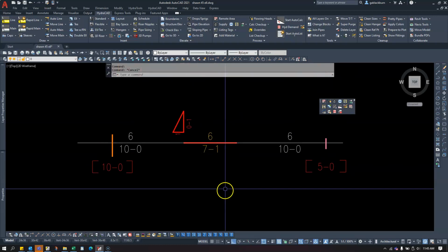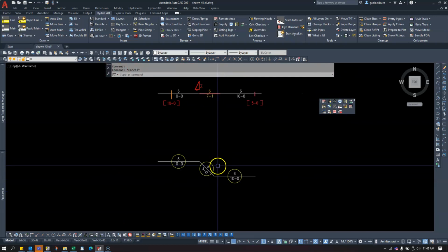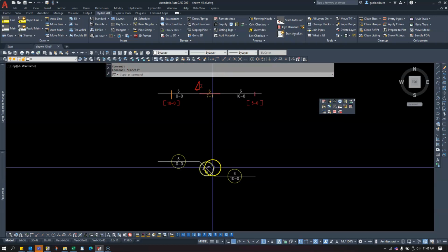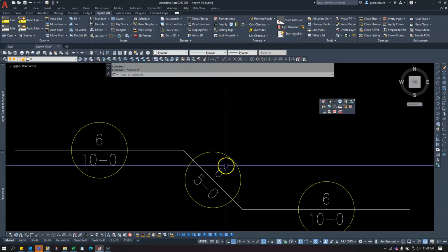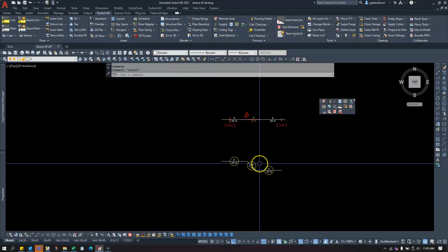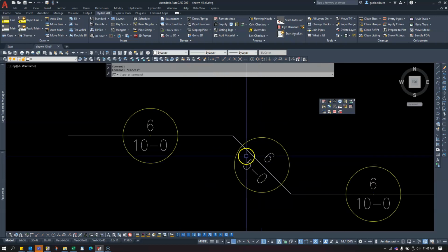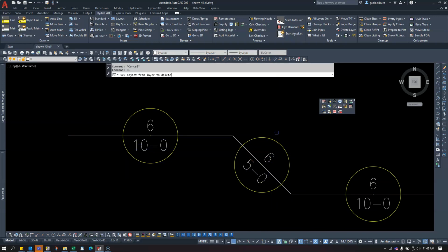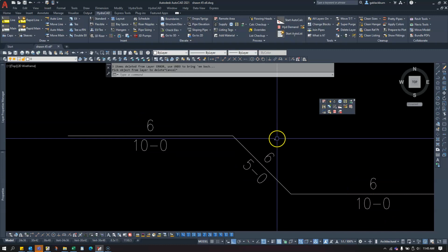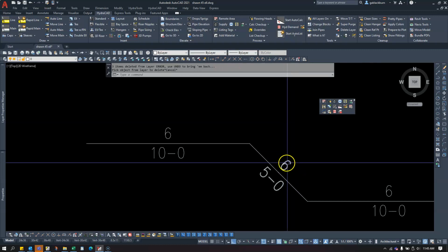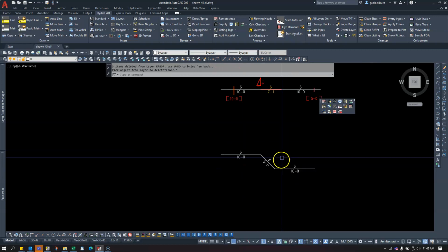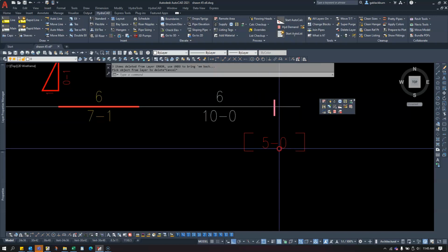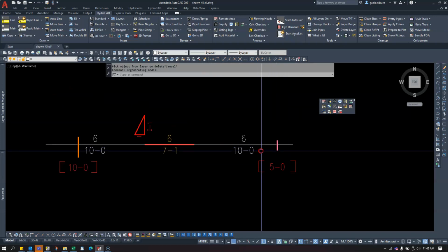Now the other thing I want to do is make sure that I have a pipe that's changing, that I want to show my 45-degree grooved couplings in here. So I'm going to use this pipe to do that. Let's first delete all of the yellow circles. So I'll type in DL to delete all in the layer. I'll pick the yellow circle, and that gets rid of everything. And now I need to show my pipe drop of 8.5 inches instead of a 5-foot drop here.